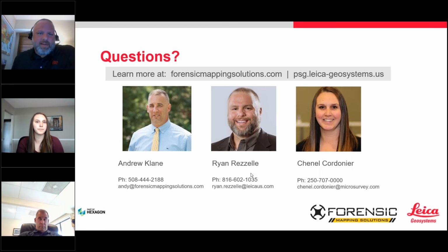But for me, I was trained first in total stations, came up through laser scanning. I now work with all of it. I definitely think that the RTC is a game changer as far as speed on a scene, but there's the flexibility you get from being aerial and shooting down over different circumstances, different terrain. With a laser scanner, it's terrestrial laser scanning. You actually have to be there with the scanner and have line of sight, and the UAS can help overcome some of those issues. So again, they each have their place. They're both exceptionally fast, and one may be faster than the other depending on circumstance.